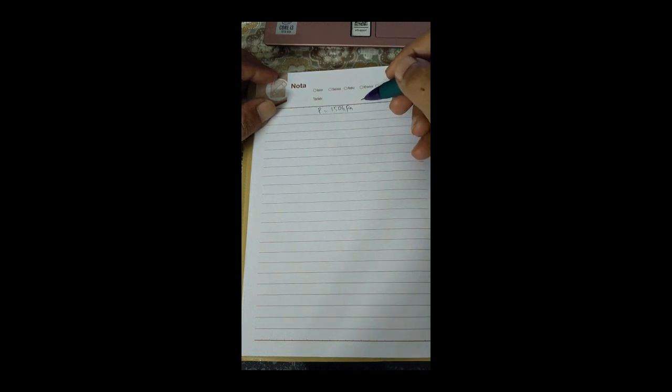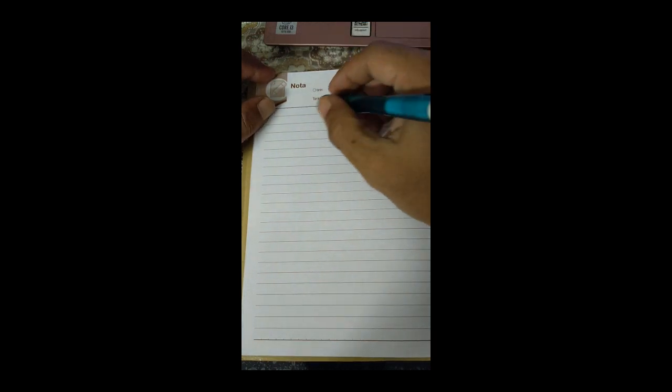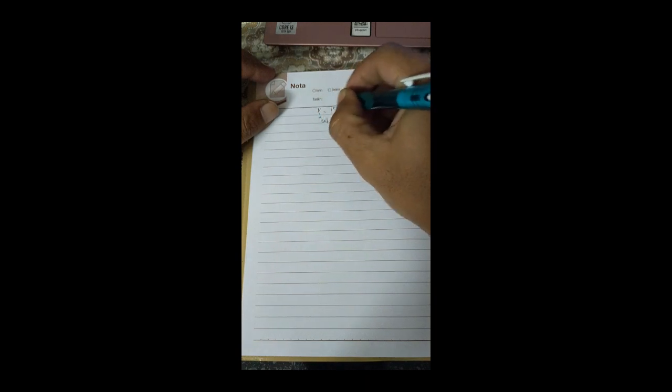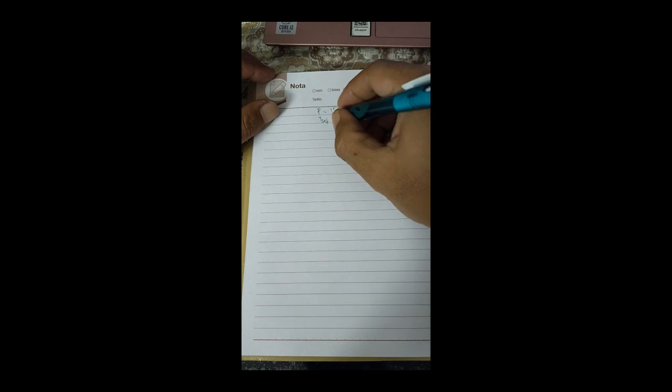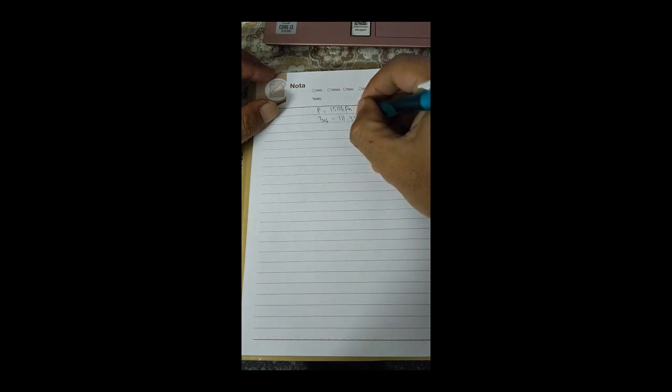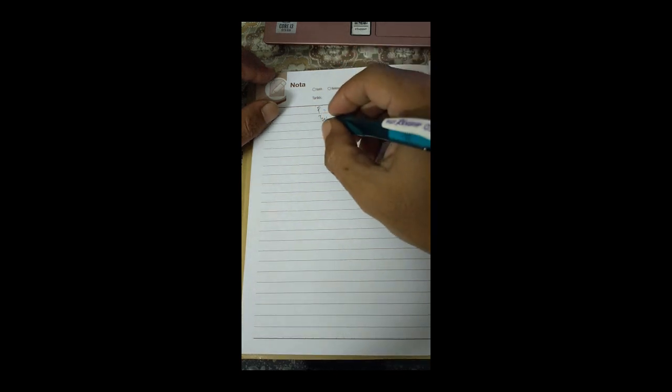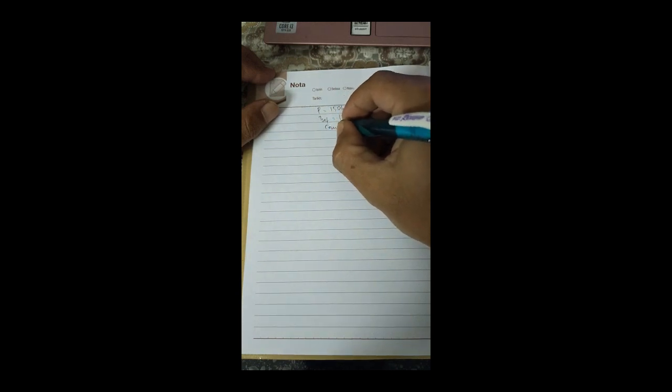Okay, and cross check the T sat at 150 kPa. How much is it? 111.35 degrees C. So the temperature inside the mixing chamber is much below this saturated condition, which means that it is a compressed liquid.